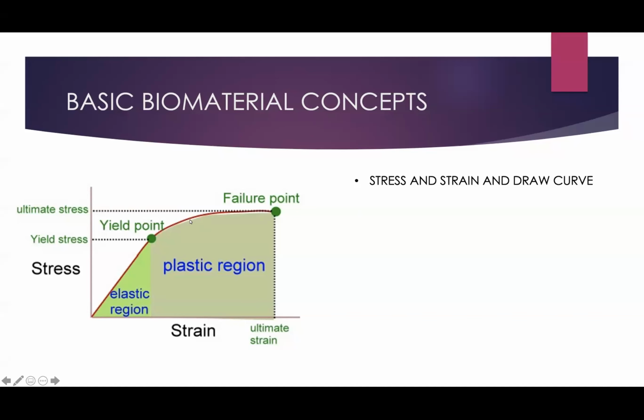And that's because as you start to change the length, you have at a microscopic level grains of atoms together which slide past one another, creating these things called dislocations. And these dislocations provide resistance to further deformation of the material, a process known as work hardening. And that's why you don't have a directly uniform appearance to the plastic zone. When you get to this highest level here, the ultimate stress or the ultimate tensile strength, you'll reach a point where the material then will start to sequentially fail until it catastrophically fails.